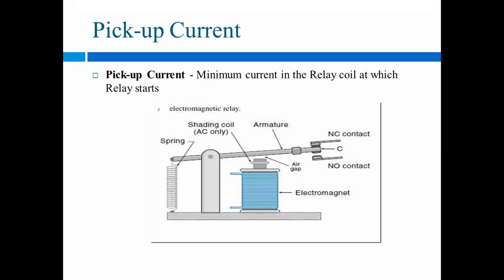Okay, so we have seen the electromechanical overcurrent relay. In that we have seen this term, that is pickup current. So pickup current means what? For electromagnetic relays, we are setting one point. That is the maximum value of current set at the relay, so that up to that point, just like the rating of the fuse, your relay will not operate under normal working conditions.